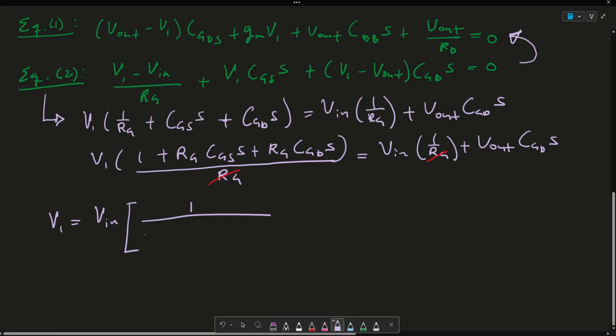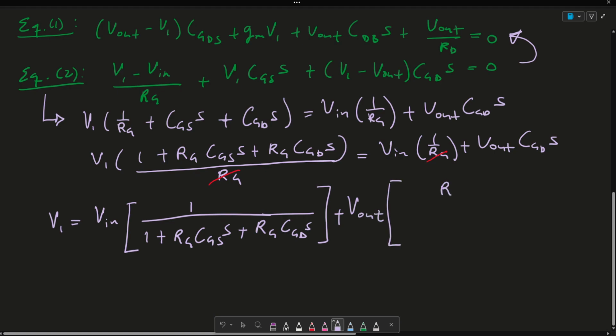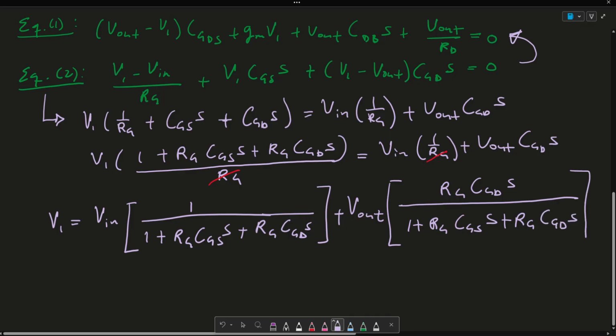And in my denominator, I get 1 plus Rg CGS times S plus Rg CGD times S, plus Vout. My numerator, my Vout is going to be Rg CGD times S over 1 plus Rg CGS times S plus Rg CGD times S. Okay, again, pause the video to make sure you're following along.